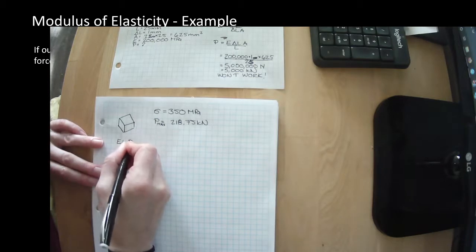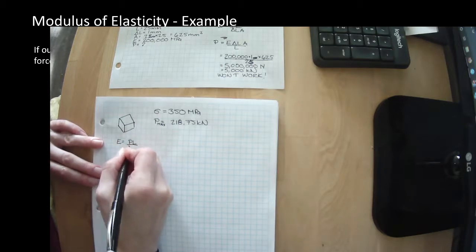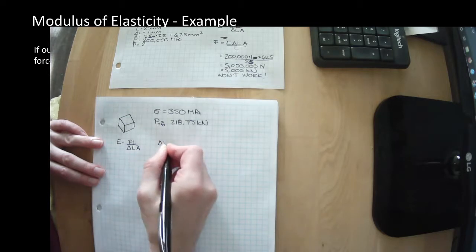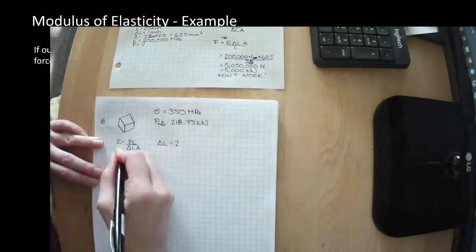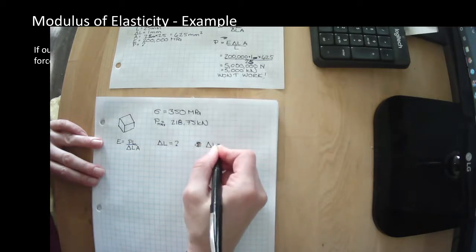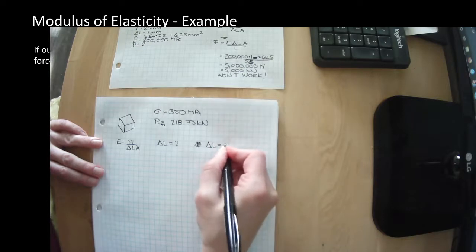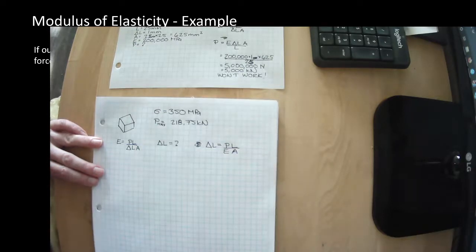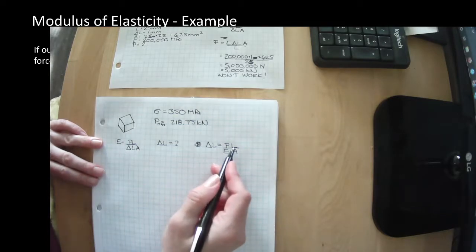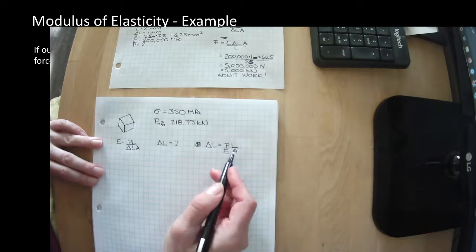E equals PL over delta L A. We want to know how much this will move. So let's rearrange our formula. We're going to get delta L equals PL over EA. We know our force, we know our original length, we know E, we know our area.